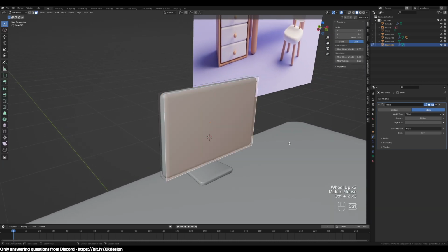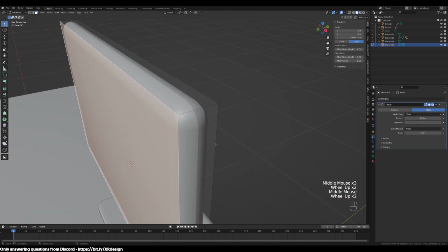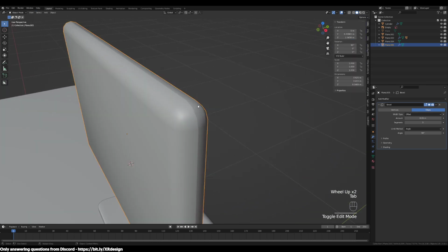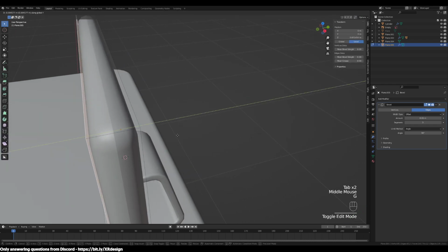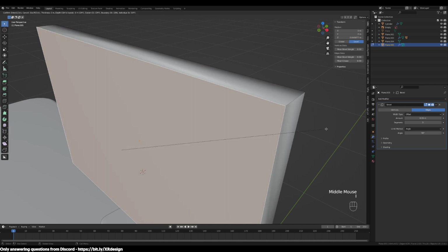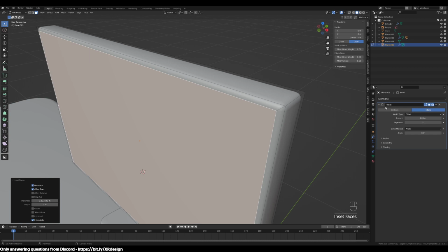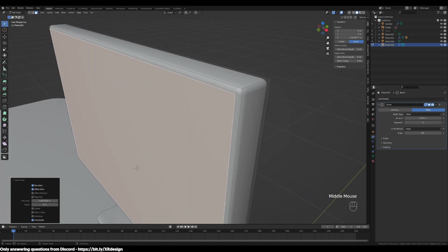I wanted to cover one more thing before we break. If the corners don't have enough distance to apply a bevel, for example, let's say I create an inset and it's only this much. What the bevel modifier is doing is trying to create a bevel for each edge that is angled.